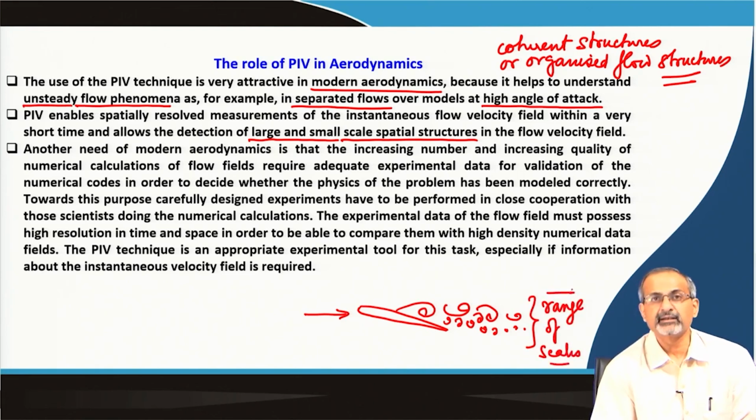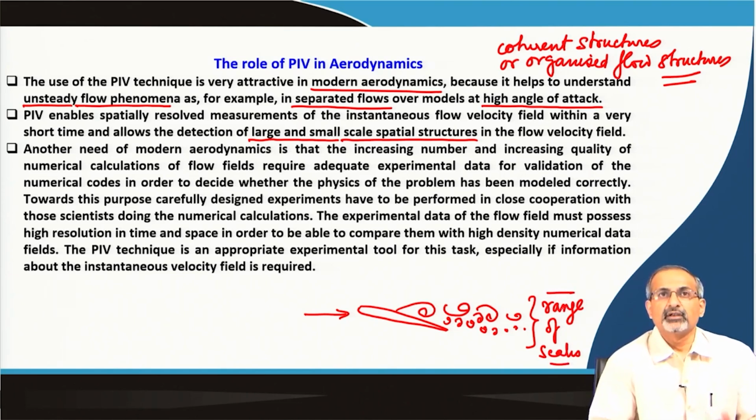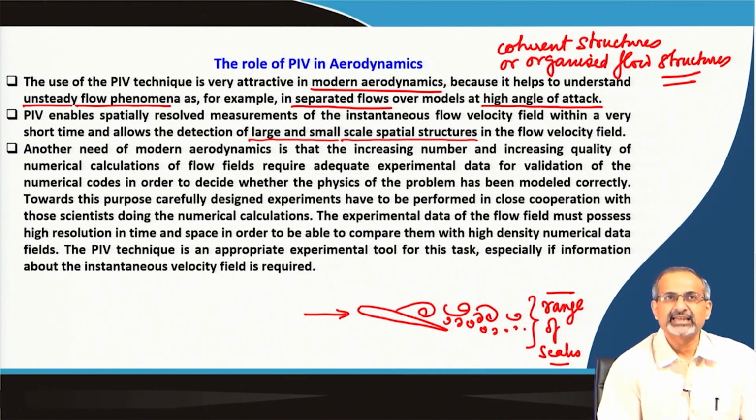and this is an inherent characteristic of a turbulent flow field, where a repertoire of large, medium and small structures coexist. So, a PIV system has a challenge of spatially resolving all these structures. Additionally, if they can be resolved with very fine temporal accuracy, then that will be an extremely ambitious goal fulfilled on both ends, spatial as well as temporal.